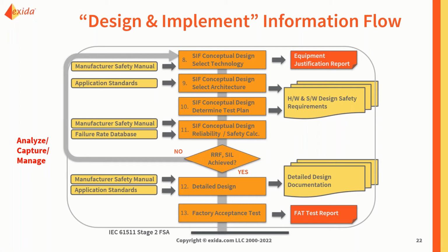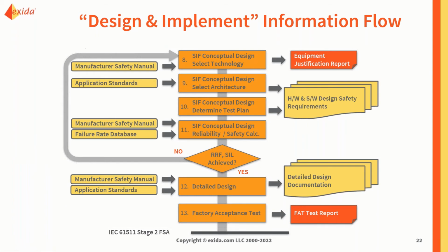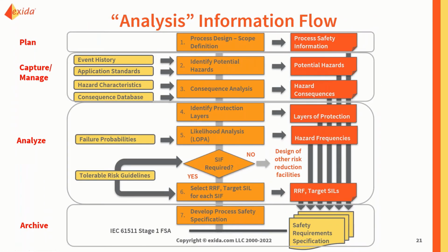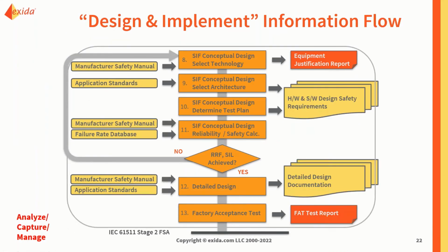So we need to go back to the LOPA to see if we have other safeguards to share the burden, to reduce the SIL requirement on that particular SIF. Then in that case, you need to go back to the specifications to update that, to properly archive that new data.